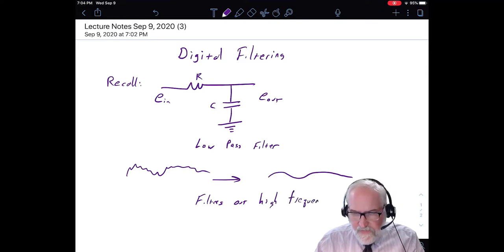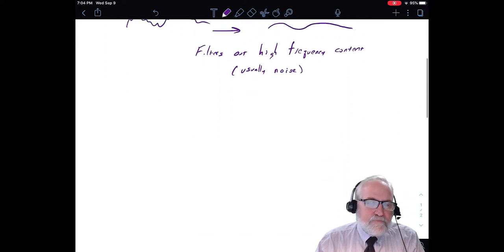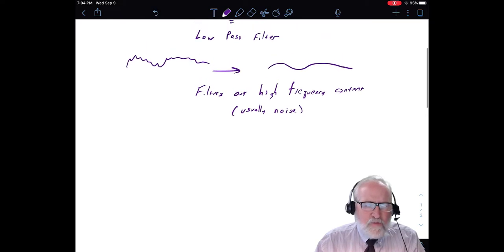You know, this high frequency noise might be coming from the AC current in the building, or a bad ground, or sometimes it's radio frequency signals that the wires in your conductors are picking up, maybe a local radio station or something like that. It happens fairly often, but particularly when we're sampling these signals in an Arduino, this can be very problematic.